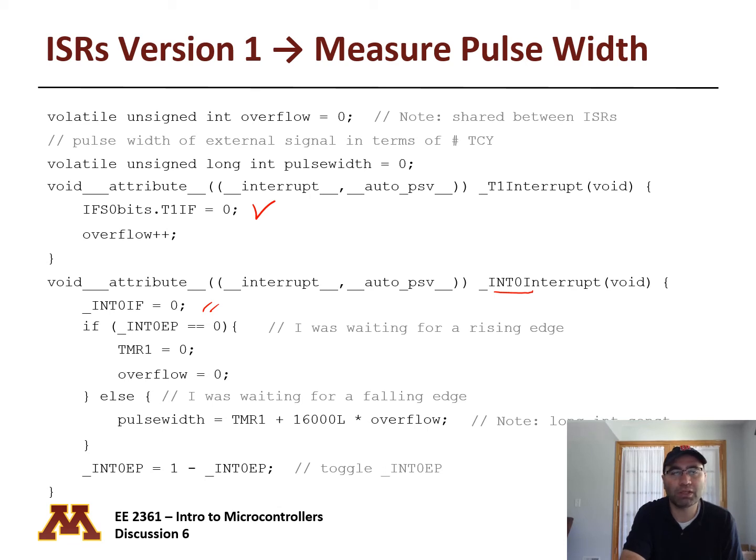If you want to get rid of one variable, you can clear the timer and clear the overflow at that point, right? So whenever we have this, we want to clear the timer value. Again, you don't have to do this. If you don't, you use the previous formulas that have count 1 included.